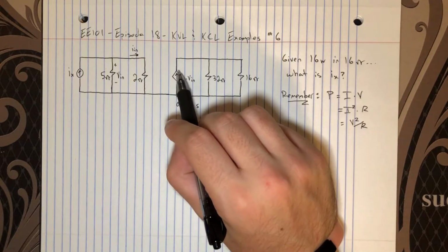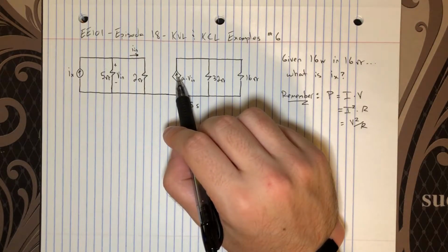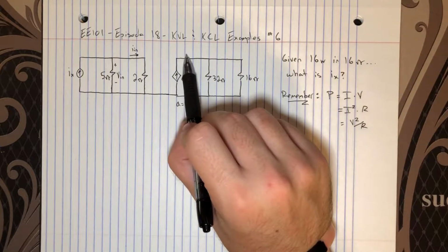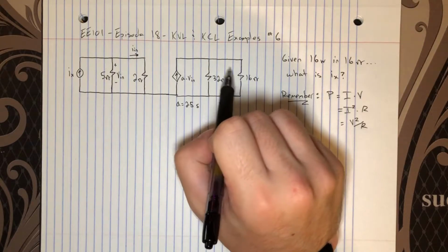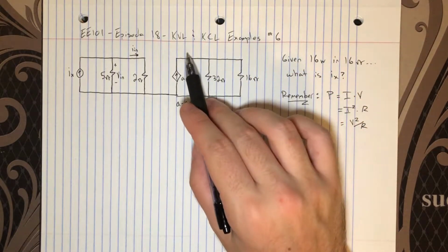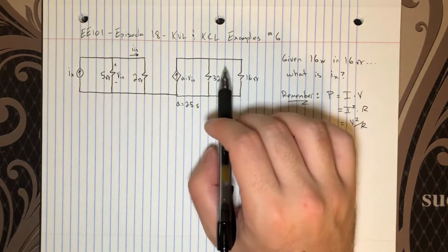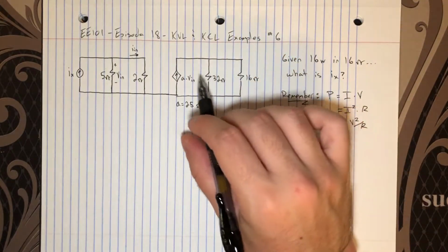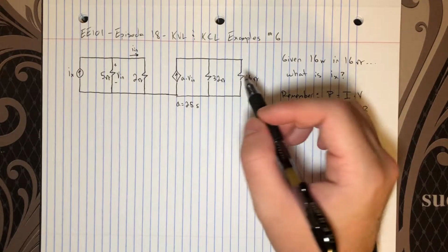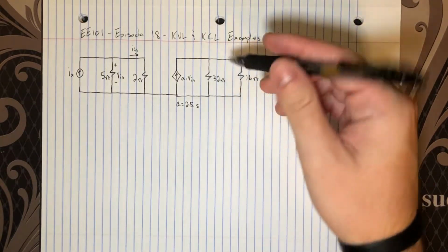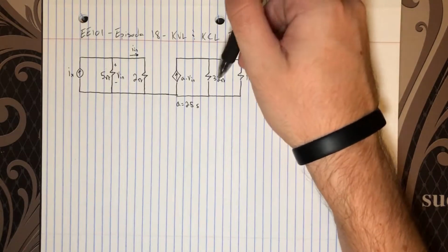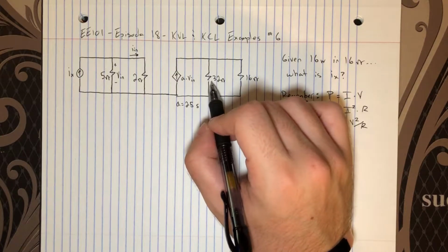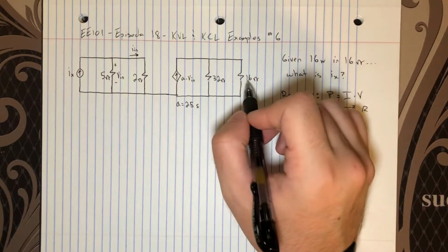This dependent current source is forcing current out of it in this direction. We know that for sure. We know for sure there's current coming to the right over here, and then it gets to these two resistors. And because however much current enters must also leave this node, we know that there has to be current traveling in this downward direction through at least one of these resistors. Right? One or both of these resistors has current flowing in the downward direction. But the fact that at least one of them has current flowing in that direction actually proves that they both do.